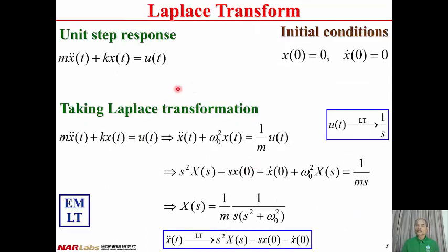If the forcing function is a unit step force, the second order differential equation can be written as m x double dot plus k x equal to u(t). And now we take the Laplace transformation of this motion equation, m x double dot plus k x equal to u(t).